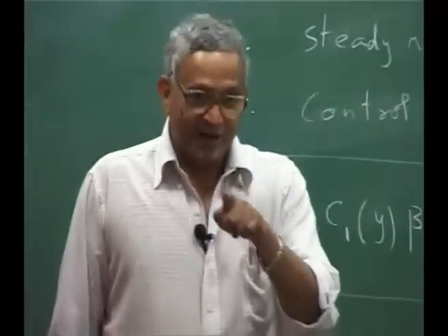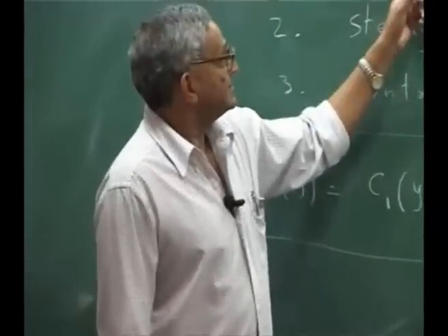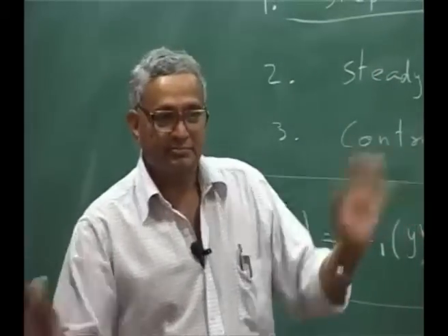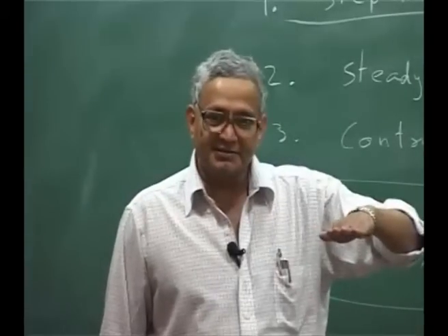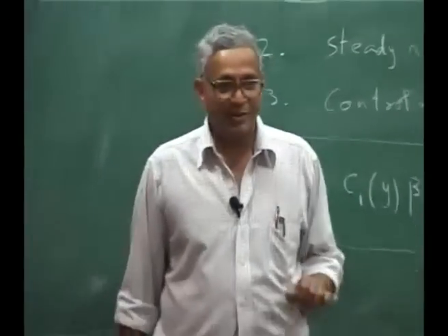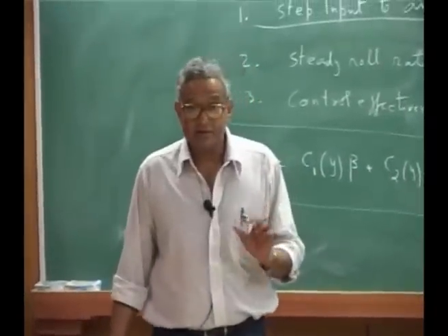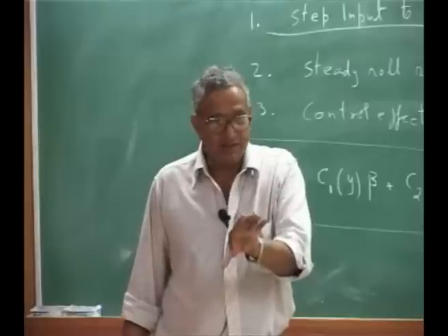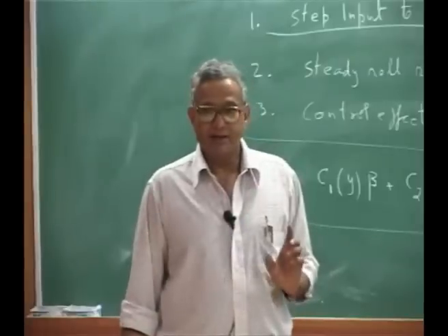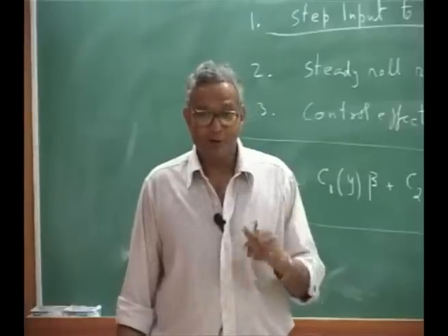Now, what you asked, that question will be answered. Now, if I deflect this suddenly, initially the aircraft is in level flight. I am deflecting it. At that time, when you deflect, what happens? Your roll rate is 0. Because you have generated a moment, you will have only roll acceleration. You will not have roll rate. You are starting.